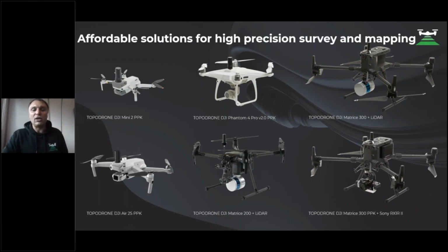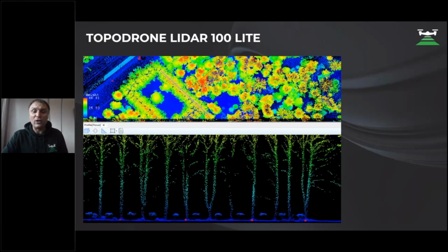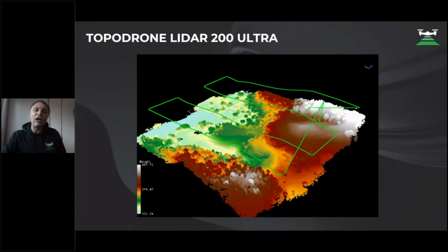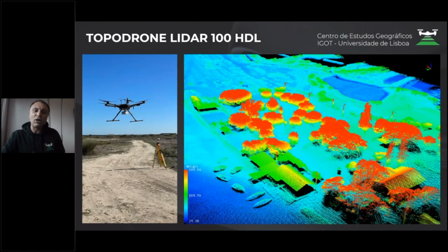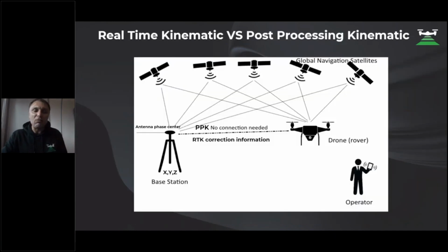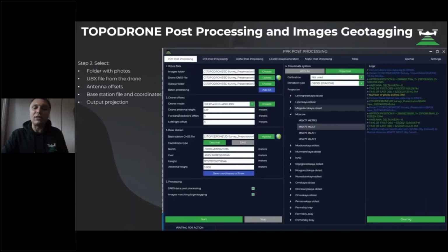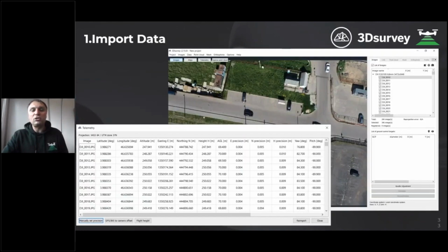And what I would like to say, why I like 3Dsurvey software. 3Dsurvey software allows to remove rolling shutter distortion from Mavic 2 Pro camera, from Mavic Mini camera, and from Air 2S camera. And rolling shutter distortion can be removed easily. What I would suggest for rolling shutter camera, you need to fly with a double grid mission. It provides the best results and very stable results. But of course, you can use only simple grid mission for flying, and you will achieve the same results.